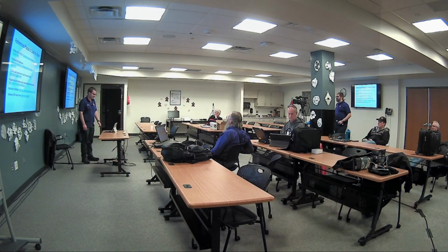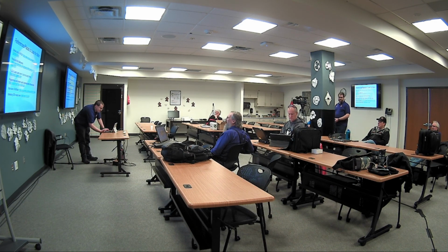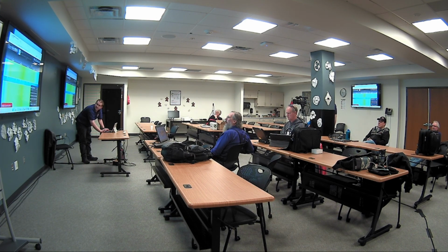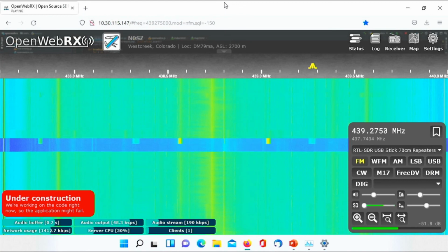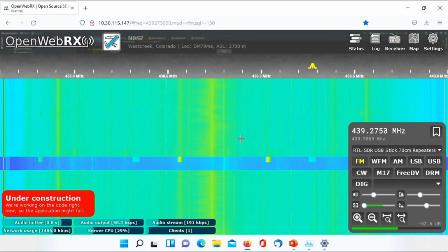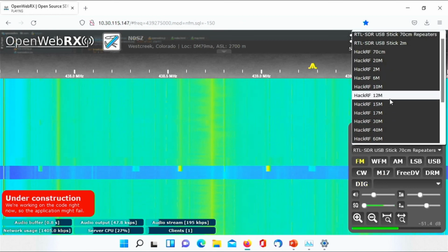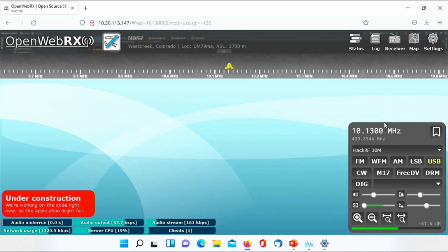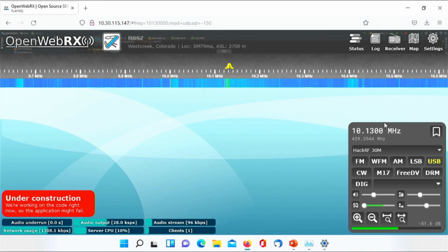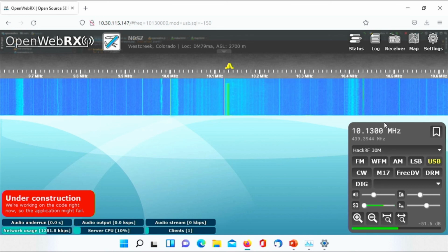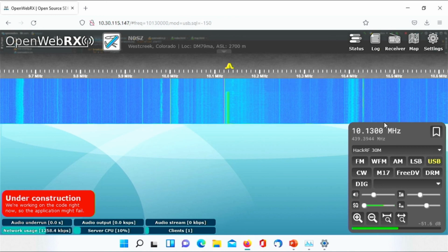Oh, that's a bummer. I don't know why that is. Yeah, so that's what it looks like. The WebSDR software, this is running on a Raspberry Pi tucked in the bottom of a rack. It actually has 2 different receivers connected to it, so we can pick whatever frequency we want. And a lot of these SDRs are very wideband. We weren't sure how this was going to go at a radio site because you have a lot of noise. And with traditional radios, you'd put a front-end filter on. You can't do that here because you're trying to receive from DC to 2 gigahertz. There is no filter. But it actually works really well.